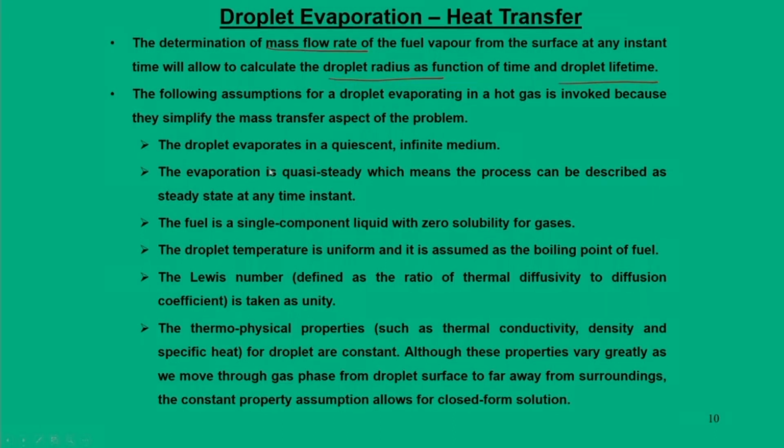In similar philosophy, the following assumptions were considered. The droplet evaporates in a quiescent and infinite medium. The evaporation process is quasi-steady, which means the process can be described as the steady state at any time instant. The fuel is considered as a single component liquid with zero solubility for gases. The droplet temperature is uniform and it is assumed at the boiling point of the fuel.